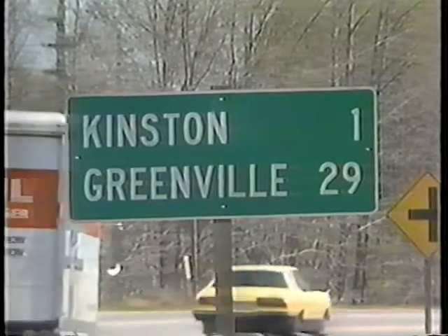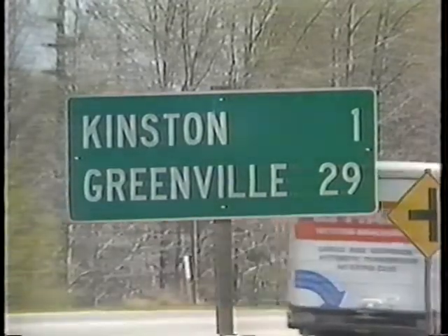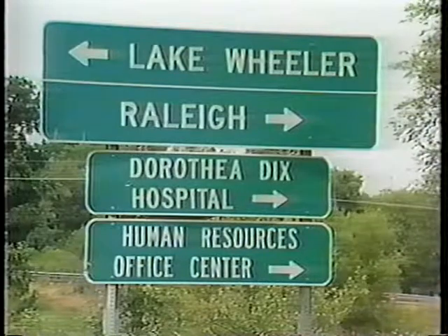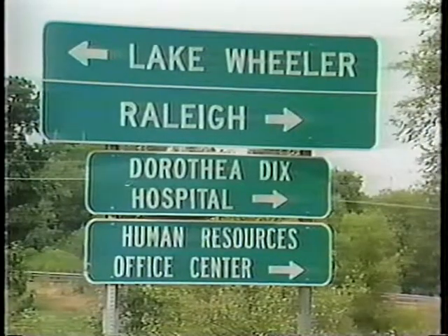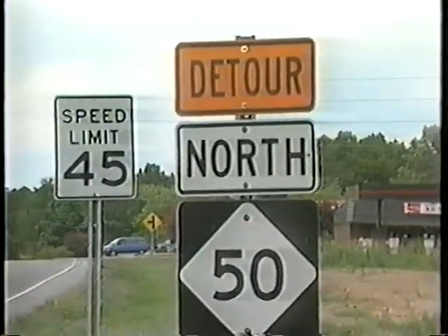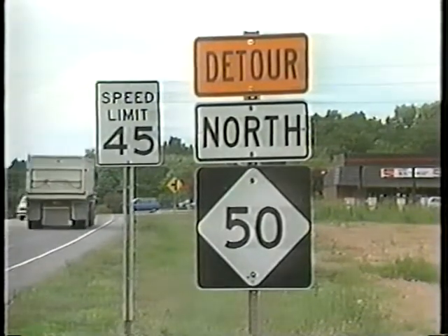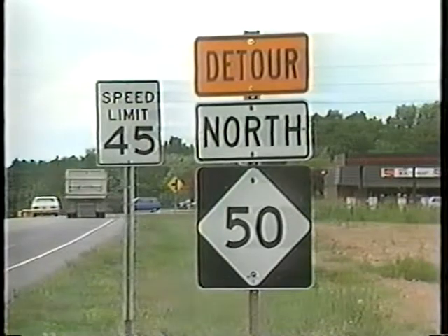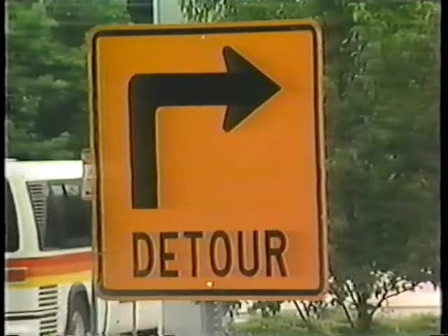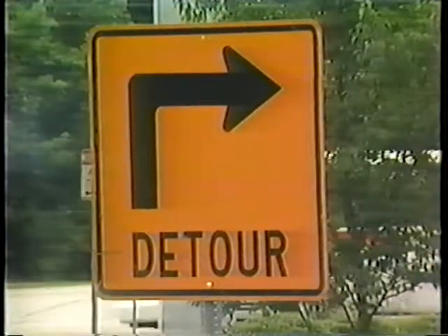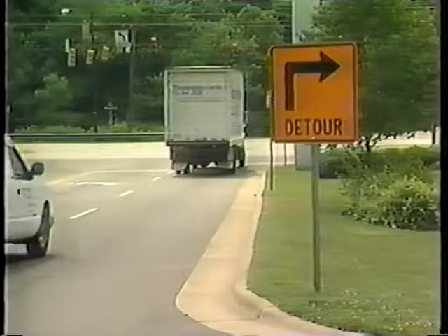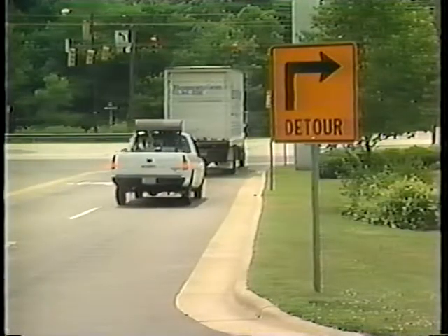Guide signs show destinations, directions, services, points of interest, and other geographical or cultural information. Informational signs are required at work zones for standard route markings when temporary route changes are necessary. Directional signs and street name signs are used with detour routing and may have a black legend on an orange background.